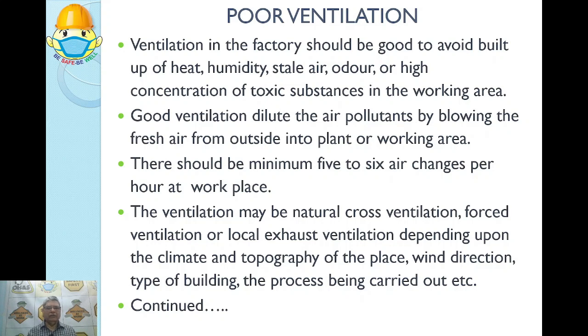If it is not possible, then you can have the forced ventilation, you can have the air handling units and bring inside the outside air with the help of those air handling units and the big fans. Then you may take out the air from the workplace and throw it out by local exhaust ventilation, and it all depends upon the climate and topography of the place. At some places, if your factory is at a higher level, you may get better wind. If you are positioned in a southwest way, then you get the proper wind.